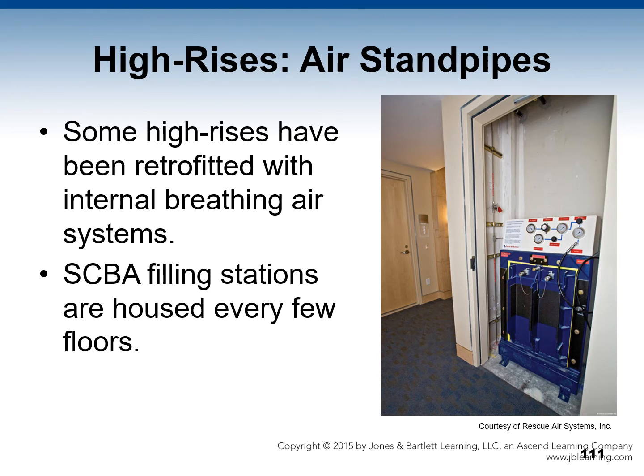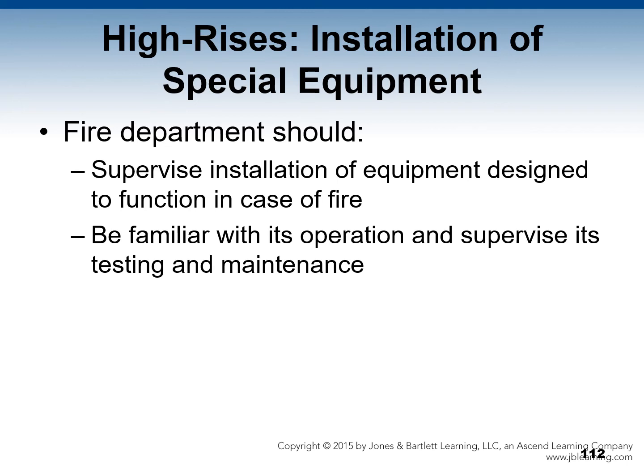Now we'll discuss air standpipes. Post 9/11, some high-rises have been retrofitted with internal breathing air systems, or air standpipes. SCBA filling stations are housed every few floors. Firefighters can avoid carrying hundreds of SCBA cylinders up to staging areas. Now there's some installation of special equipment that occurs in high-rises. Equipment designed to function in case of fire should be installed under the supervision of the fire department. The fire department should be familiar with its operation and supervise its testing and maintenance, whatever that special equipment or system is.